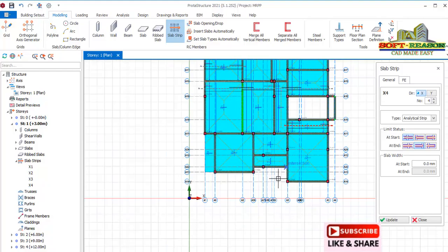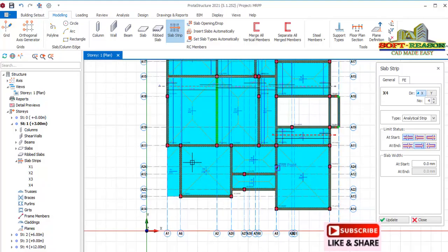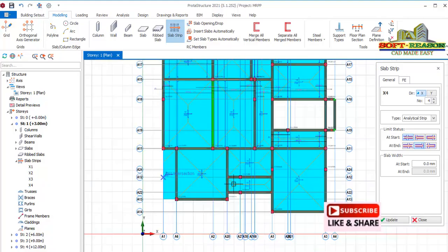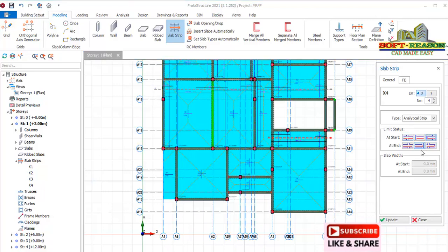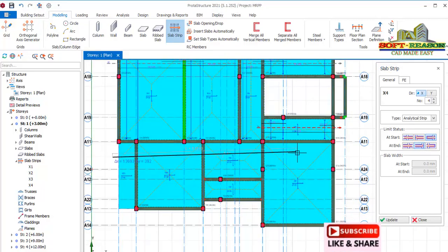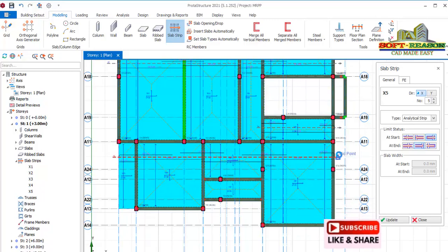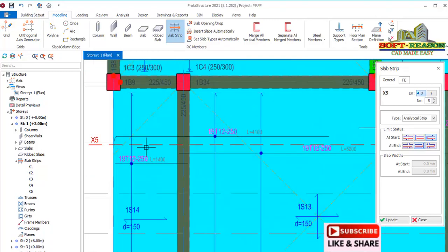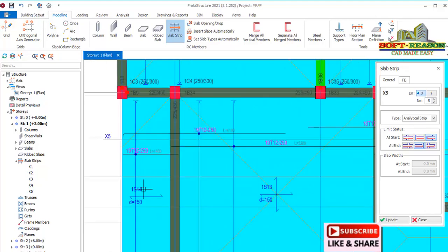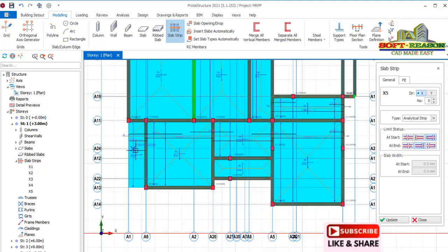So for these provisions, this is a cantilever, so we are going to start from cantilever and end at bulb, which is outside. So you pick right there to that point and end there. So you can see this cantilever rebar has been generated successfully, just like this.